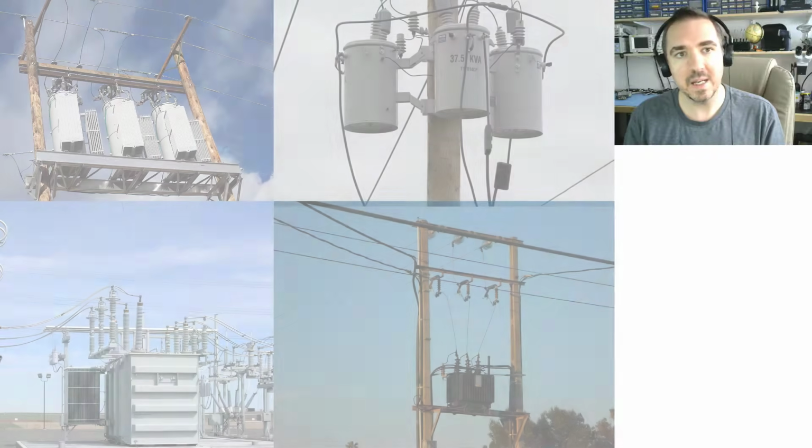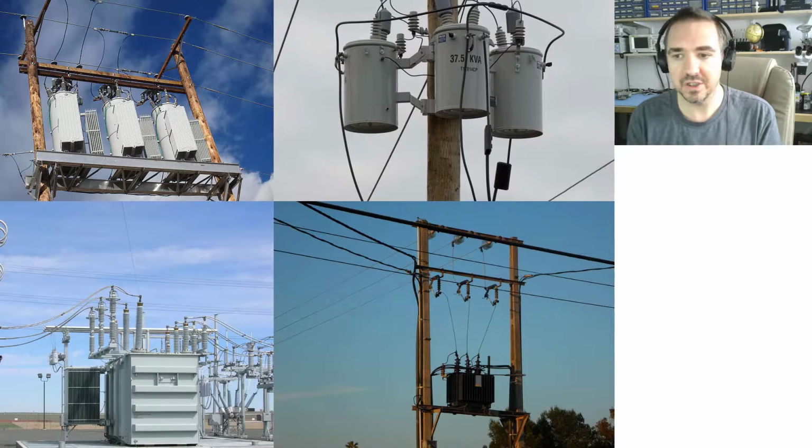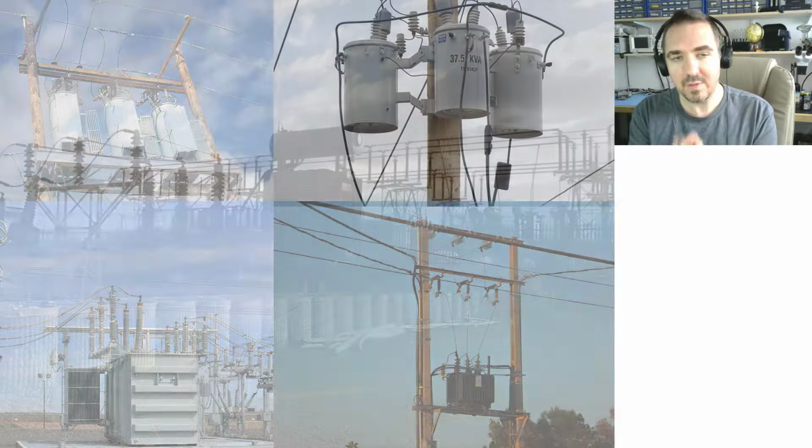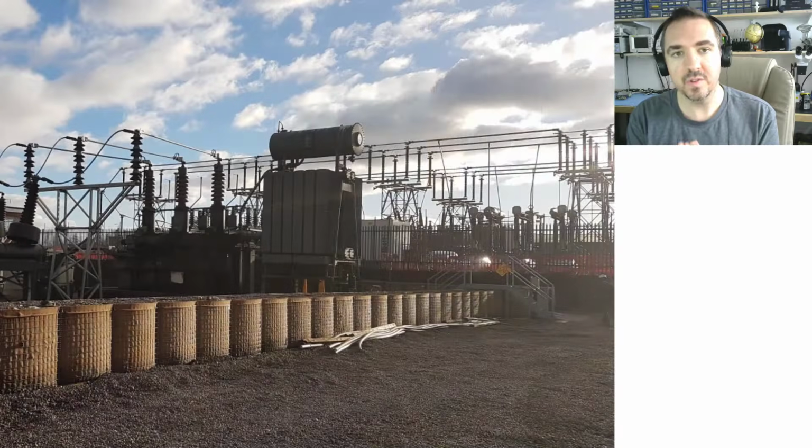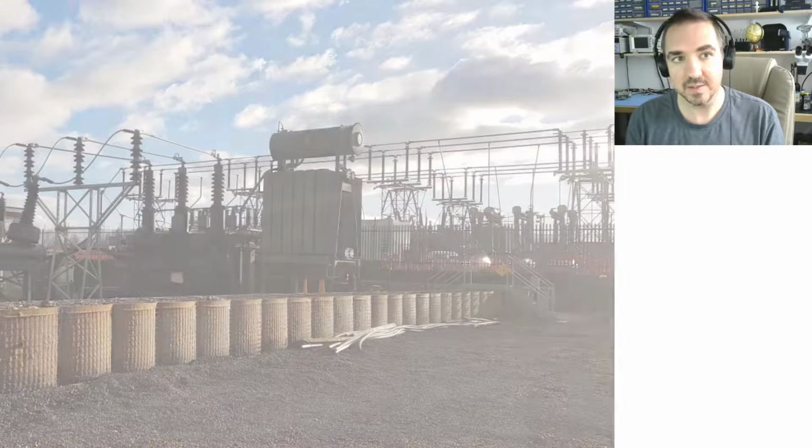Now, up to this point, we've assumed that the transformers have no impedance, so they do not appear in the per unit equivalent circuit, and the transformer simply steps up or steps down the voltage and current. However, real transformers do have an impedance, and we need to be able to handle this in per unit analysis.